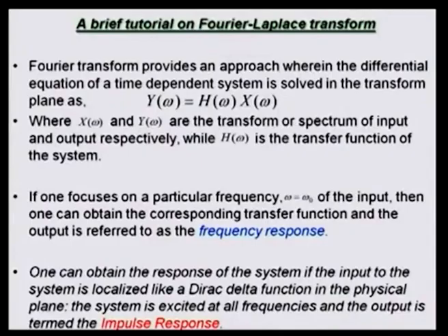The interesting major difference between impulse response and frequency response is that frequency response would actually latch on to the frequency of excitation. So, it is like a forced vibration problem, whereas the impulse response allows the system the freedom to choose its so called natural frequency.